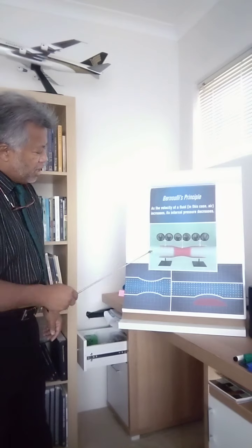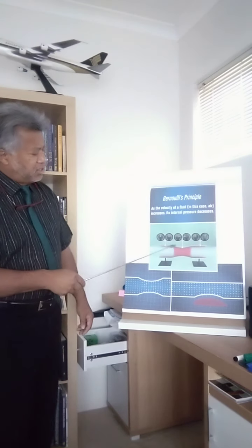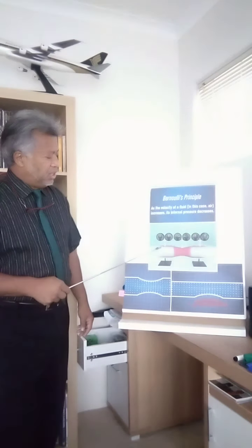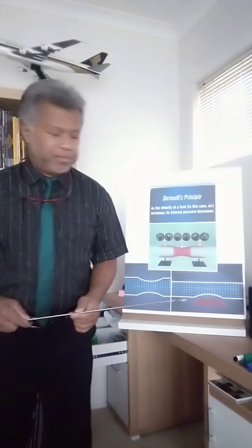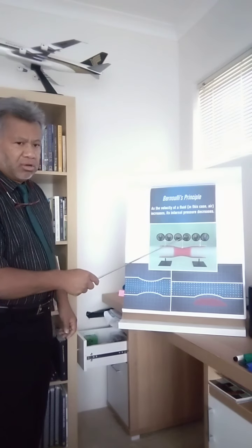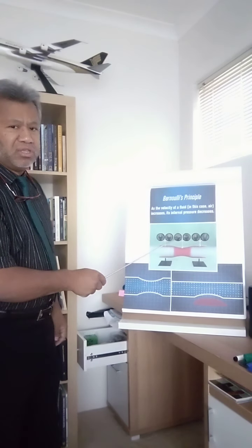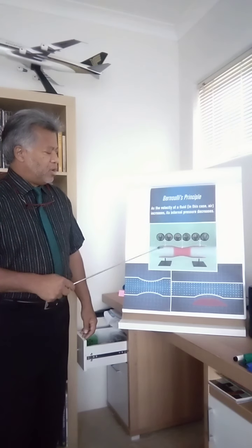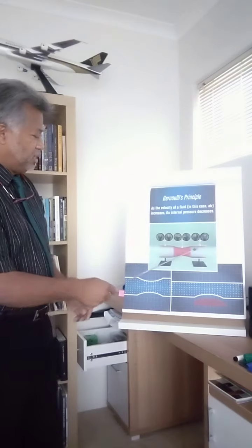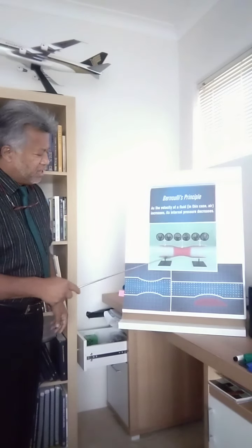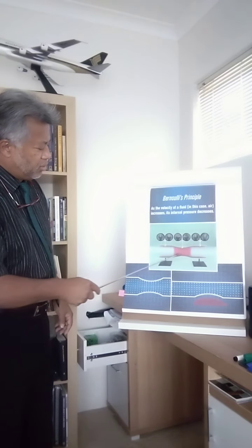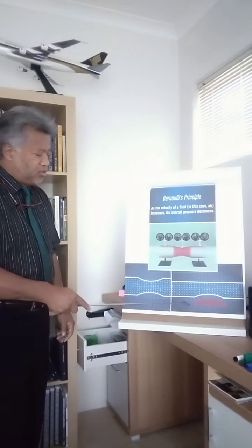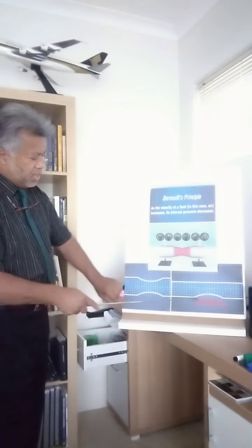The air is flowing through here, and as the venturi or the pipe narrows, it's forced to increase in airspeed, which creates a pressure reduction. Of course, on the other side, it goes back to the normal pressure and velocity. So if you can imagine this venturi with the curvature where the air is forced to accelerate, similarly it can be applied to the camber of a wing aerofoil in this state.